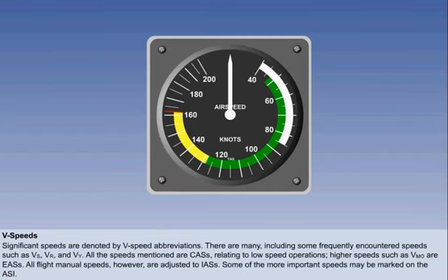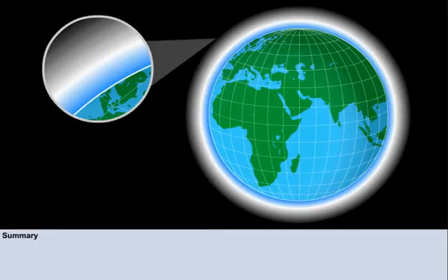The atmosphere is the element in which aircraft operate, and it is important that you understand how the properties of the air, pressure, temperature and density change throughout the part of the atmosphere in which you fly. It is particularly important that you understand the concept of dynamic pressure and how it is involved in many of the aspects of the principles of flight. The next lesson deals with basic aerodynamic theory, in which you will see the application of some of the facts you have just learned.